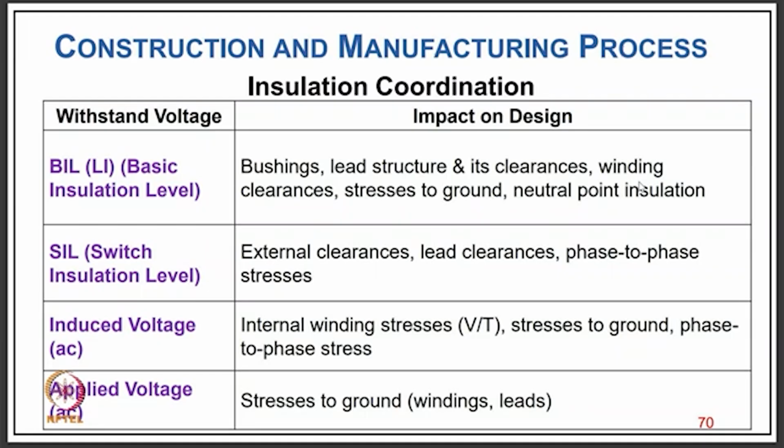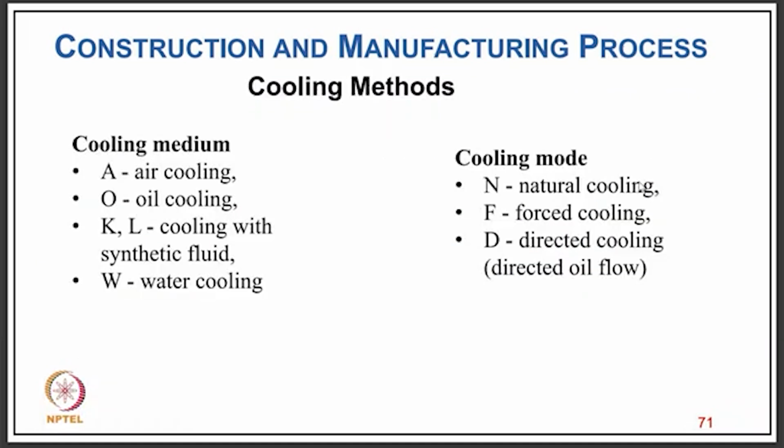Then in SIL, the switching insulation level, we have the external clearances, lead clearances, and phase to phase stresses. Then we have induced voltage, with internal winding stresses, stress to ground, and phase to phase stress, and applied voltage, that is stress to ground for winding and leads.